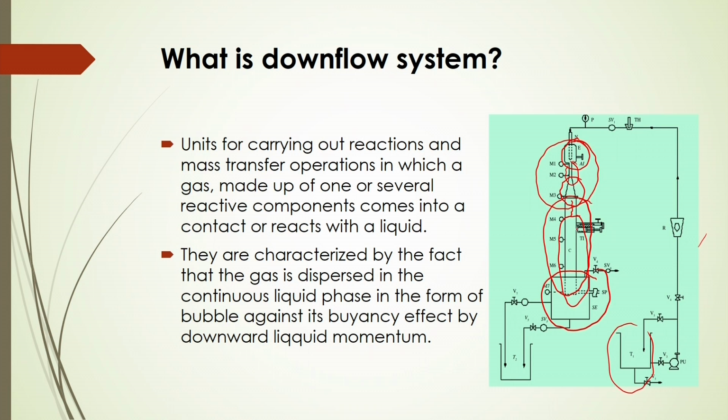As the gas bubbles move downward, they have more residence time. Even at this location there will be intense mixing of gas and liquid. Based on this concept, there is process intensification by having more residence time, where some physical operations require more contact time or residence time of the gas bubbles. In this way you can use this downflow system.